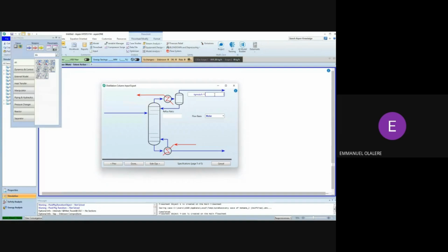So, vapor rate. I don't know the value of my vapor rate, or do I? Let's see. The preliminary design specifications require a reflux ratio of 6.06. So we specify that, 6.06. And they give me an overhead product of 226 pounds per hour. So this is my overhead product over here, 226 pounds per hour.